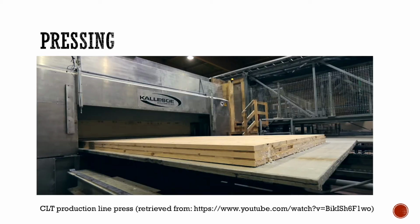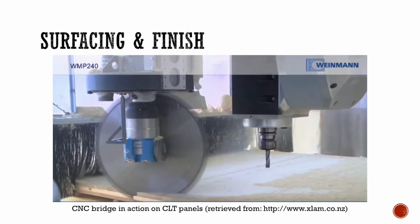Now that each layer of lumber has been sprayed with adhesive and laid up, they are placed in the assembly press. The entire sandwich of layers is then pressed vertically and horizontally in a large hydraulic press to ensure proper bond development is achieved between all the individual pieces. After pressing, the panel is dried and moved to a large industrial sanding machine, which will fine-tune the final thickness of the product to the exact dimensions required for the project. Tolerances on these large industrial sanders are often as accurate as 0.1 millimeter.